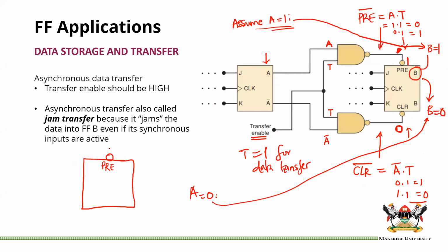So the idea is that the information coming, if it is to be active, the information coming from up here should be 0. So if I'm writing this on the outside, I have to write it as pre with a bar. And that tells me that actually that input is active low. When a 0 is coming in, it will be inverted into a 1 and it will perform whatever it performs. But we are looking at it